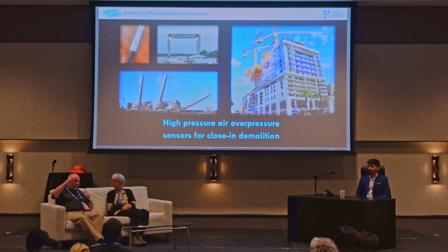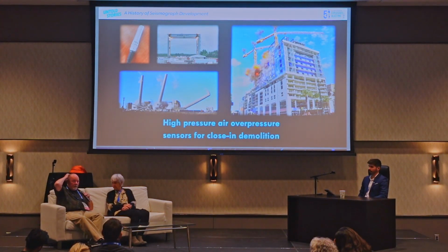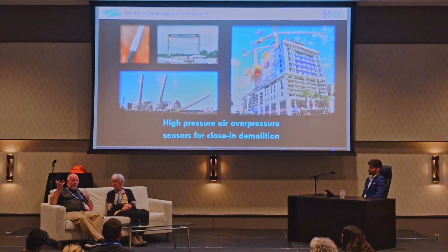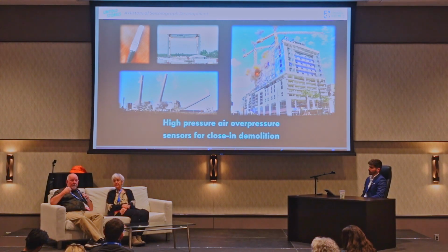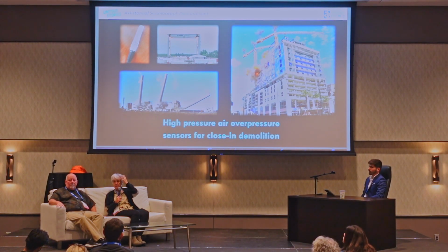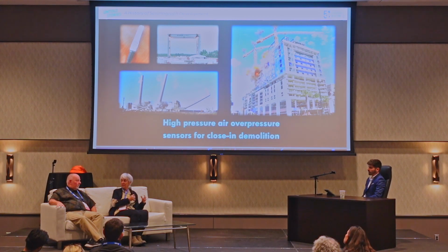One of the things you need to be careful about when you're doing PSIs that large is that we always recommend you get extension cables to get the microphone away from the data collector, because those high pressures hitting the data collector will cause problems and potentially mess up your measurements. I forgot to mention that. We keep all our seismographs clustered at least 100 feet away.